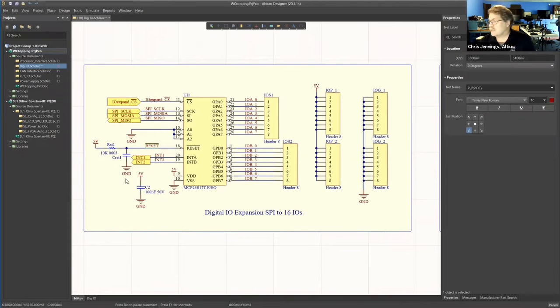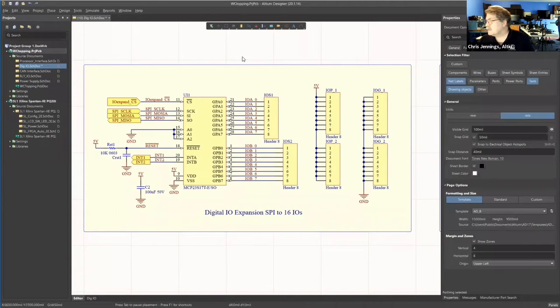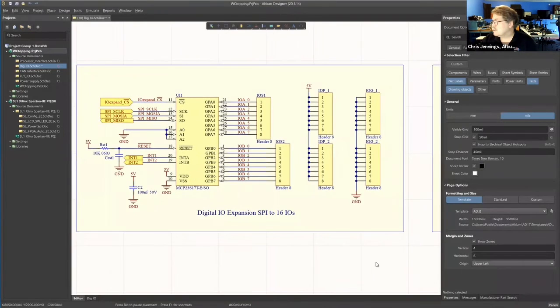Well, here, this is a resistor and a capacitor. So when the power comes up initially, U11 is in reset mode. And that's a very constant, easy thing. It's very easy to see. It's easy to understand what's going on. And here's all your IOs. And again, this allows someone who doesn't know your design to look at this and fairly quickly grasp what's going on in this particular page.